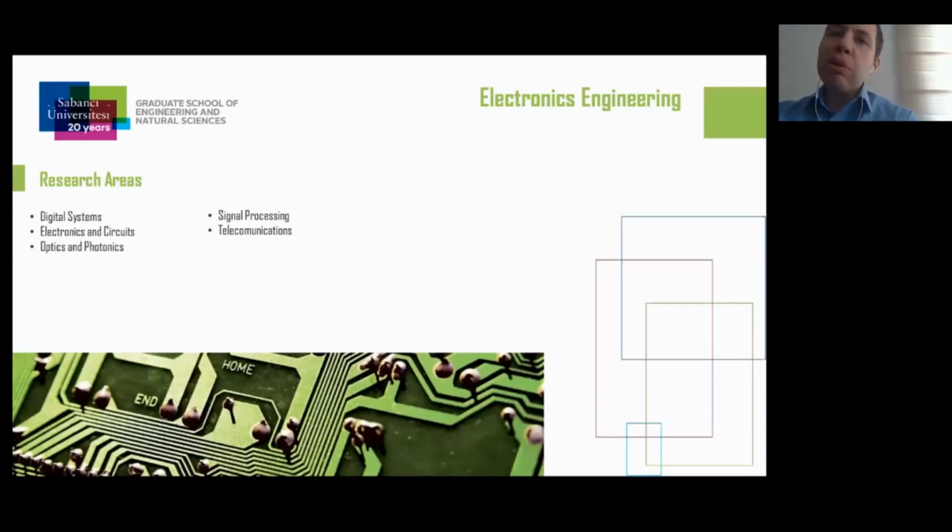So if you look into the simple example of a cell phone, starting from the moment that one starts speaking and vibrating those air molecules, it hits a transducing element, and somehow those vibrations are turned into an electrical signal in the analog domain, which is conditioned with specific circuitry and converted into a digital domain for processing.